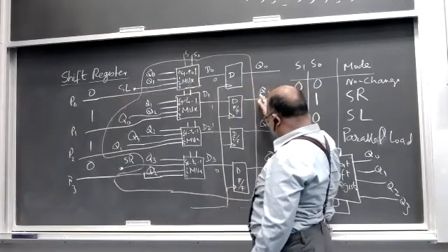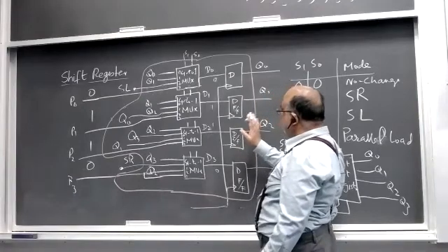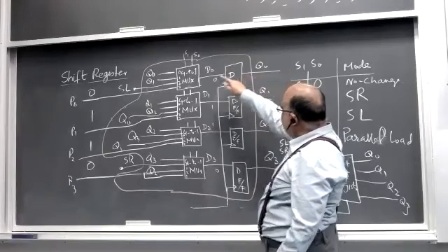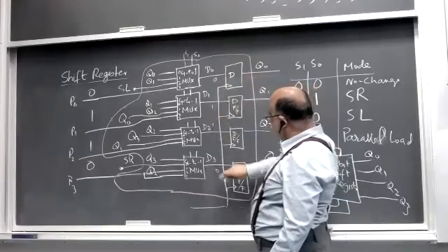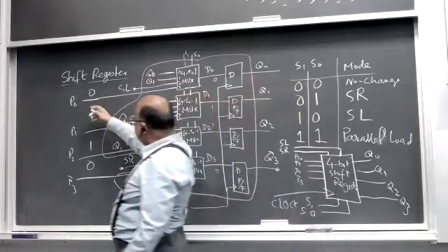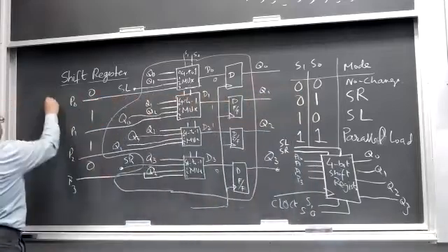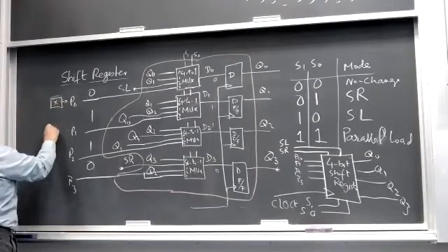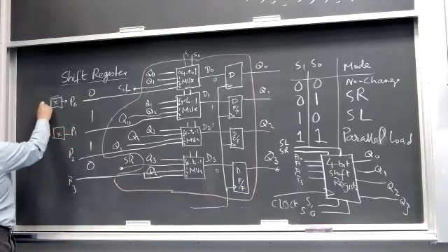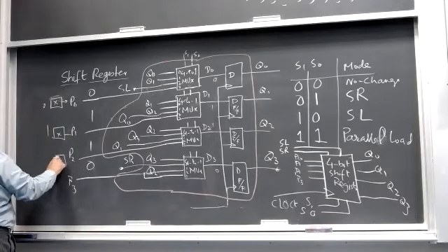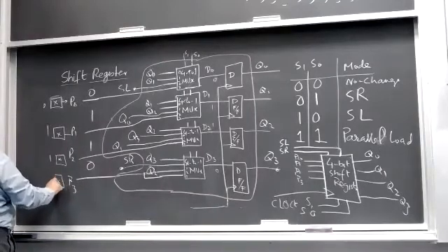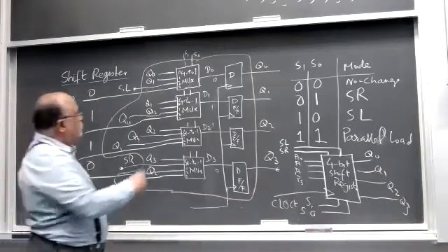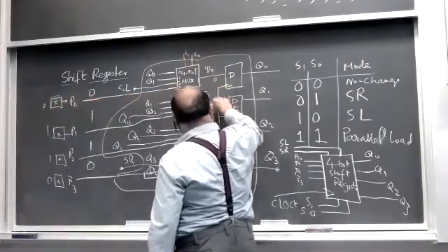कि आप मैं इस रजिस्टर में को वैल्यू तो लोड करूं, उसके बाद पहले मैं शिफ्ट लेफ्ट राइट नहीं कर सकता इसको. आई वांट टू लोड सम नॉन वैल्यूज. तो जब मैं 1 1 करूंगा तो ये 0 1 1 0 हो जाएगा, जो मैंने यहाँ पे वैल्यू स्विचेस के साथ सेट की हुई है, या लॉजिक स्टेट्स मैंने दी हुई. यहाँ पे मैंने 0 1 1 0 सेट कर दिया. अगर आप हार्डवेयर में रहेंगे तो ट्रेनर के स्विचेस से आपने इसको सेट कर दिया है. तो जब आप इन दोनों को 1 1 करेंगे तो यहाँ पे भी 0 1 1 0 आएगा.